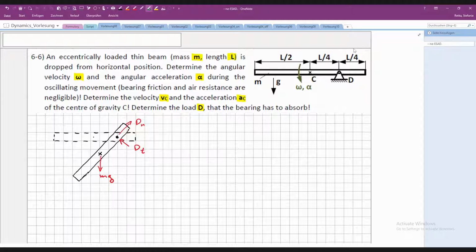Then in green, I will draw the motion of the beam. These are not loads, okay? Only red vectors are loads and will be considered in our equilibrium conditions, but we need to describe the direction of motion, because in this depicted position, the beam could move upwards or downwards, this way or that way. We have to choose a direction. And depending on our choice, we can draw the inertial loads.